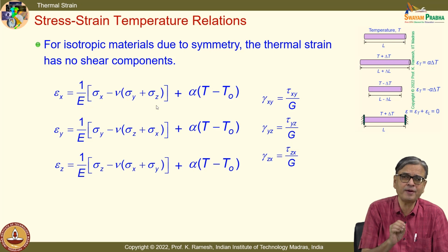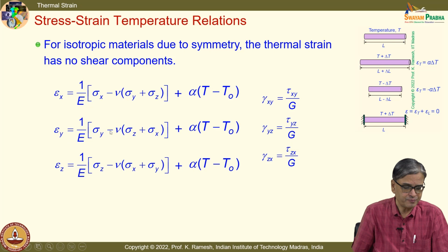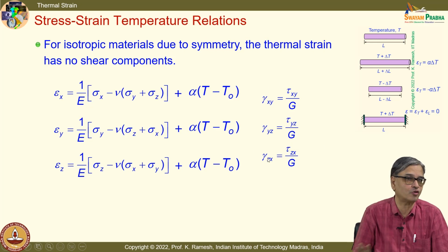For a given problem, identify which stress components do not exist, knock them off. Do not simply write from your tension test that strain is simply sigma y by E. That is a mistake; that is applicable and valid only for a tension test. And fortunately, for your shear strain, there is no influence of temperature on it. So, it becomes a lot clearer.